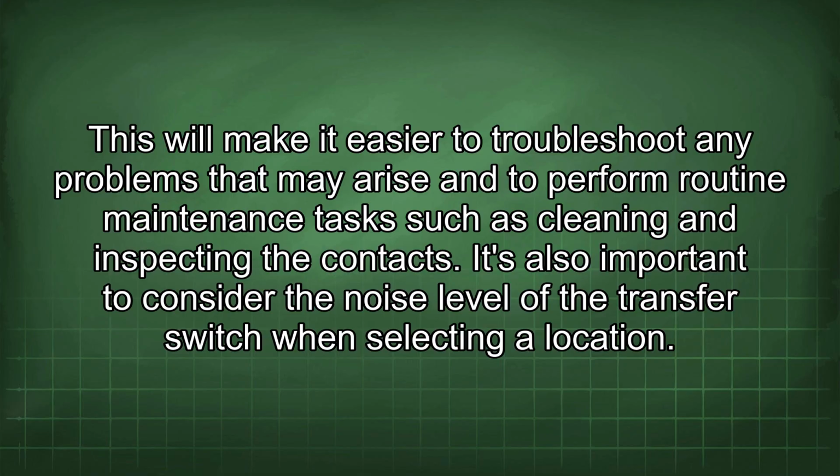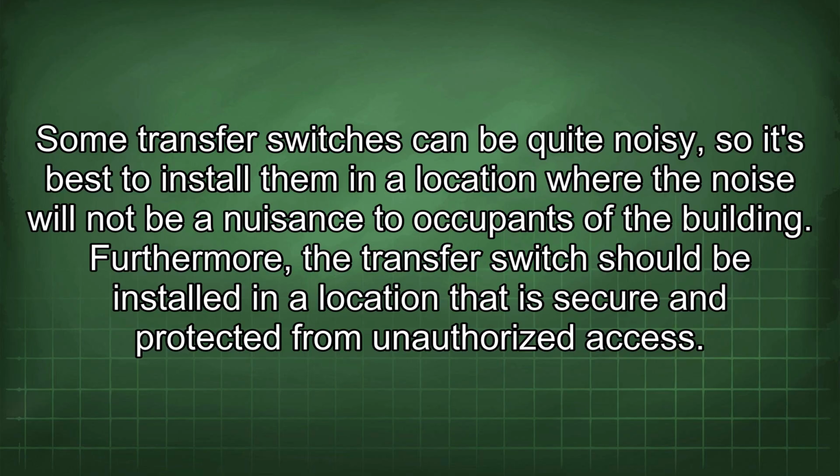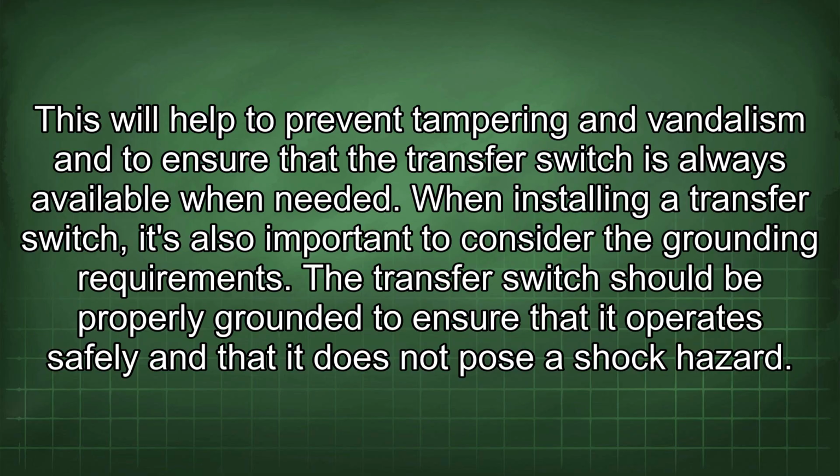It's also important to consider the noise level of the transfer switch when selecting a location. Some transfer switches can be quite noisy, so it's best to install them in a location where the noise will not be a nuisance to occupants of the building. Furthermore, the transfer switch should be installed in a location that is secure and protected from unauthorized access. This will help to prevent tampering and vandalism, and to ensure that the transfer switch is always available when needed.